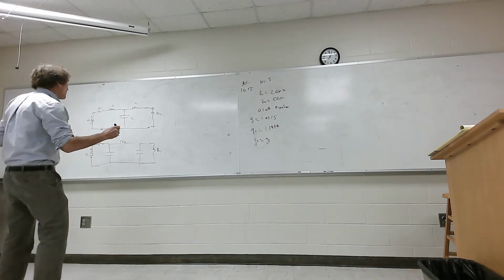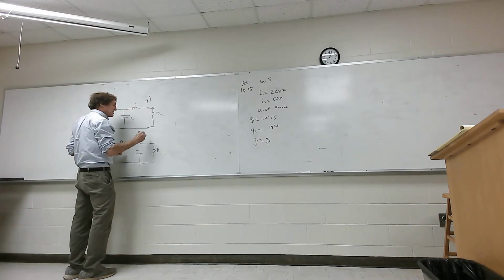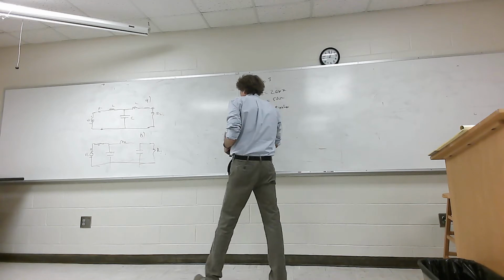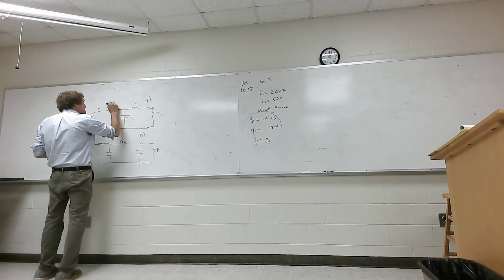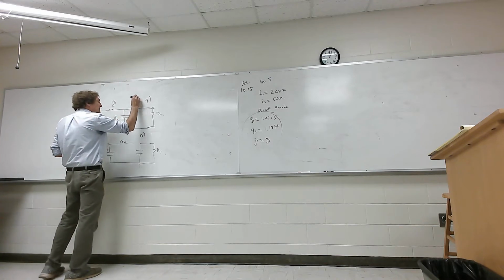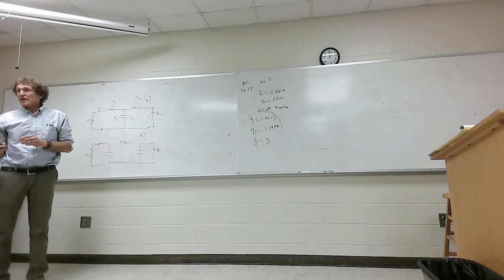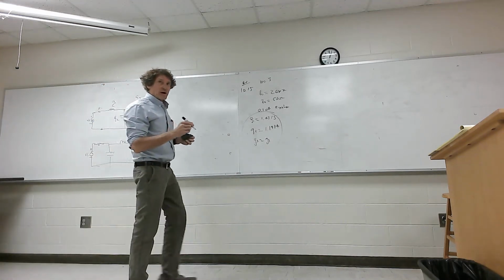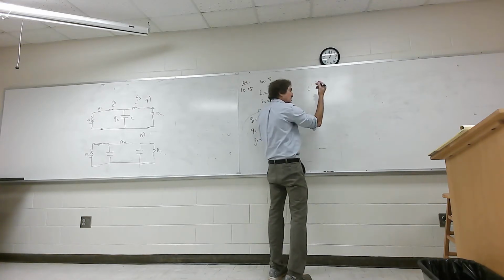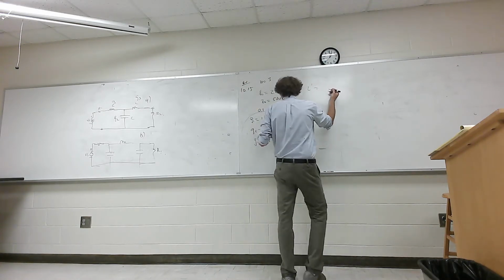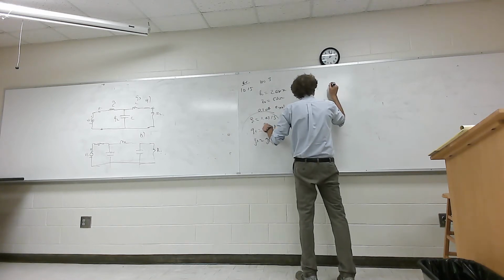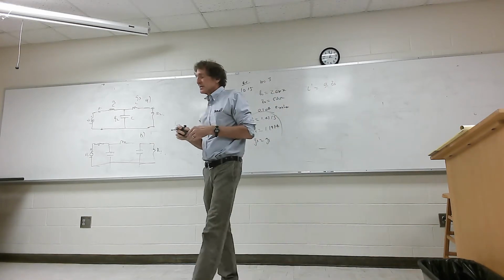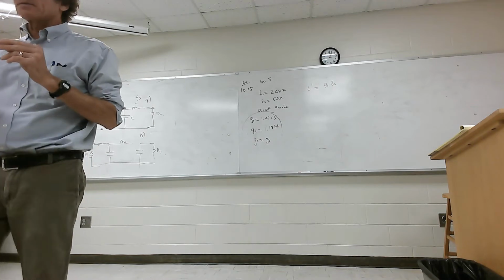So for this one, we'll call this A and this B. Now for A, we've got these values. Technically, in his book, he calls this G1, this G2, and this G3. Anytime you're dealing with an inductor, the way you get the L prime value, and this is an intermediate step, it's simply the value of that element, which would be G1, times Z0. That gives you a normalized value, because of the normalization. Y'all follow me on this class?